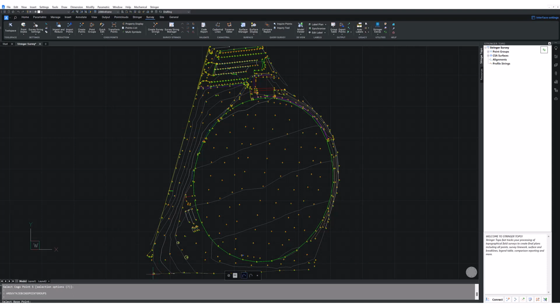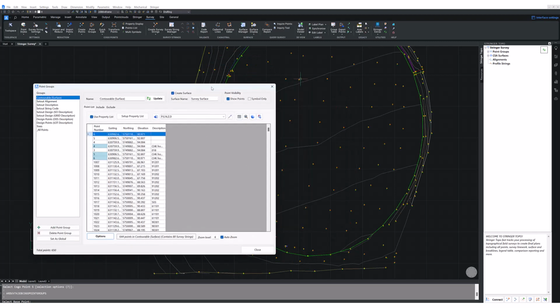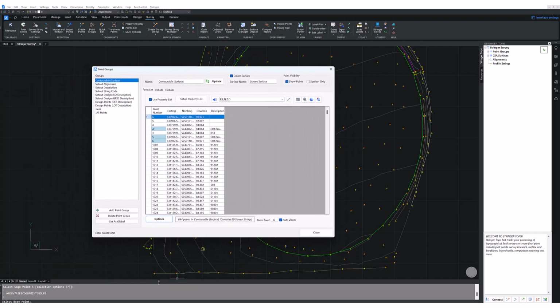In this case, I'm scaling it, so I want to do it from the bottom corner here, and then I'm able to enter the value that I'm wishing to do it by. In this case, I'll be doing a scale factor, but if you were to choose rotation, you will be able to decide the rotation and such. Now the default value here is 2. Let's say I wish to scale it up by 1.5. I am able to do so before going OK. You can see that the drawing has now scaled up by 1.5 from that base point that I had selected.